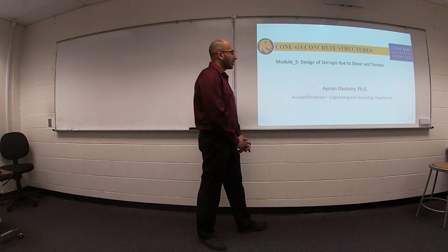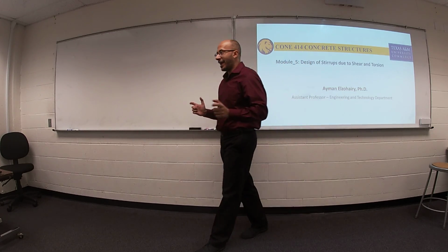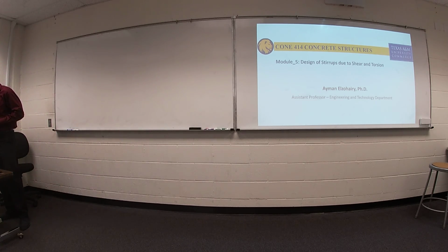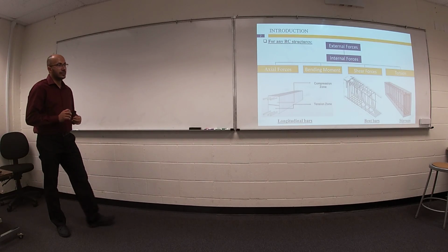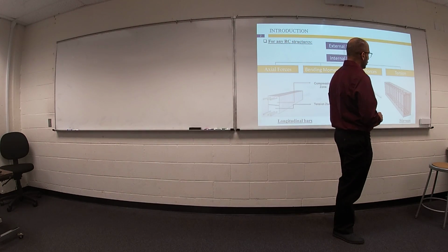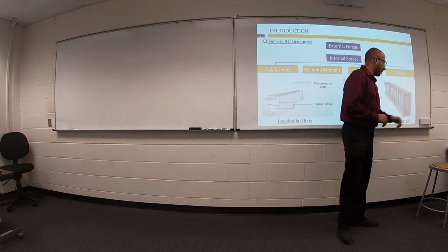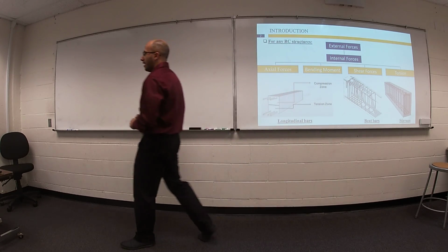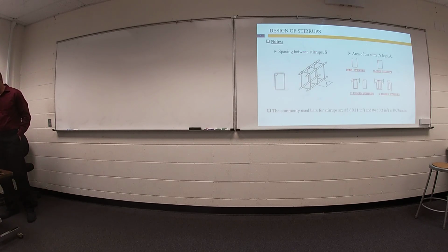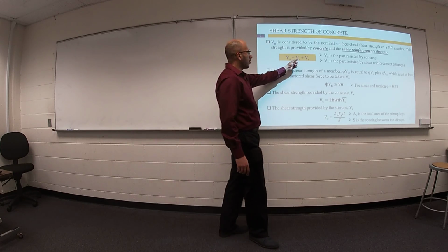How to design your reinforced concrete beam due to shear, and figure out the spacing between your stirrups. Just a reminder, stirrups are the main steel reinforcement used to support shear force and torsion. For shear, we have two contributions: one part from concrete, the second part from steel.